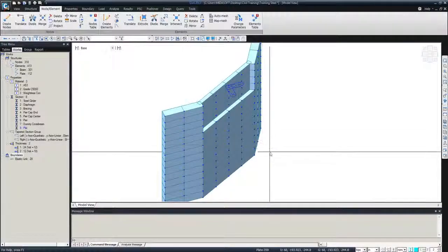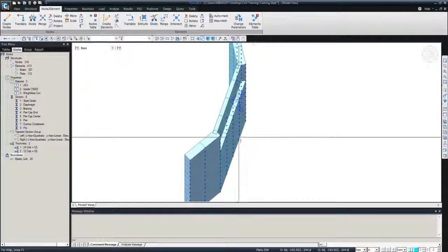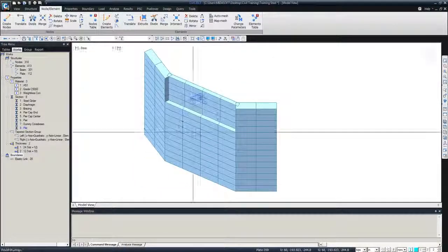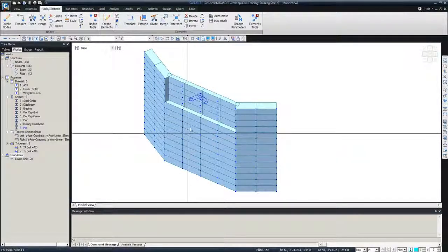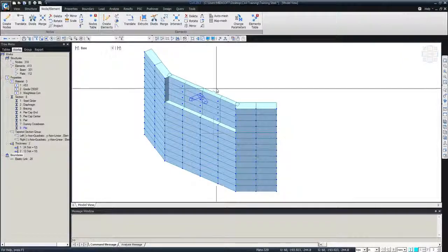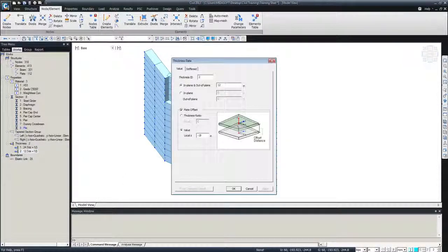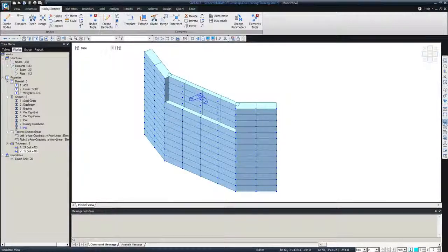As you can see, I adjusted the points or the offset option, because the same concept that I showed you for the girders or beam elements, we have for the plates, where you can just simply apply the plate offset. So you can just adjust the location with these offsets.